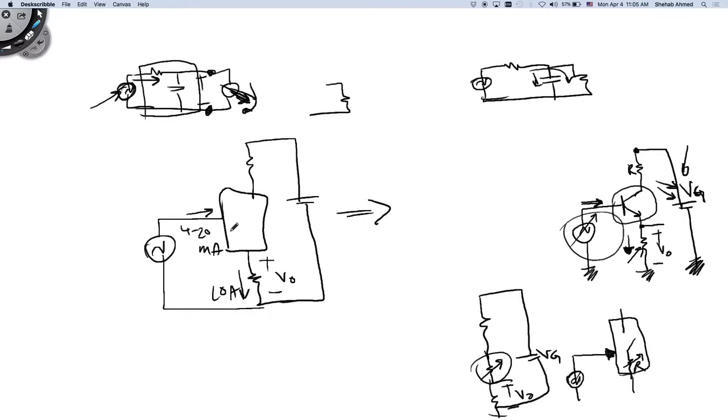You have to put some circuitry in the middle. And it cannot be a simple analog passive low-pass or high-pass filter that we studied before. It cannot be analog electronics, because in that case I'm relying on the power from that sensor to supply my load. Because again, my load now looks like this resistor, my low-pass filter looks like this, and this is my sensor. They're all connected in one circuit. I will have to do Kirchhoff current law, Kirchhoff voltage law, find out the currents. It's a simple AC circuit that we studied, right? That is not the right way to run a motor in a control process.